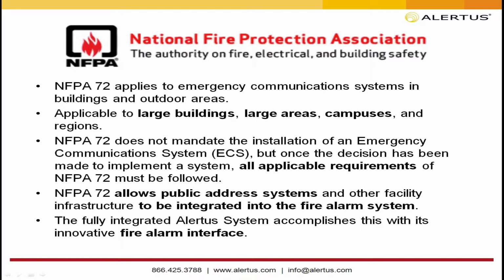That's something I would recommend for people that are not too familiar with the NFPA 72 Chapter 24 code to go out and see what their options are for creating a risk analysis. What that risk analysis would allow you to do is determine the exposure that you currently have based on your different modalities of sending out a notification. Some locations only have fire panels, so that would increase your exposure to anything else besides a fire alarm.